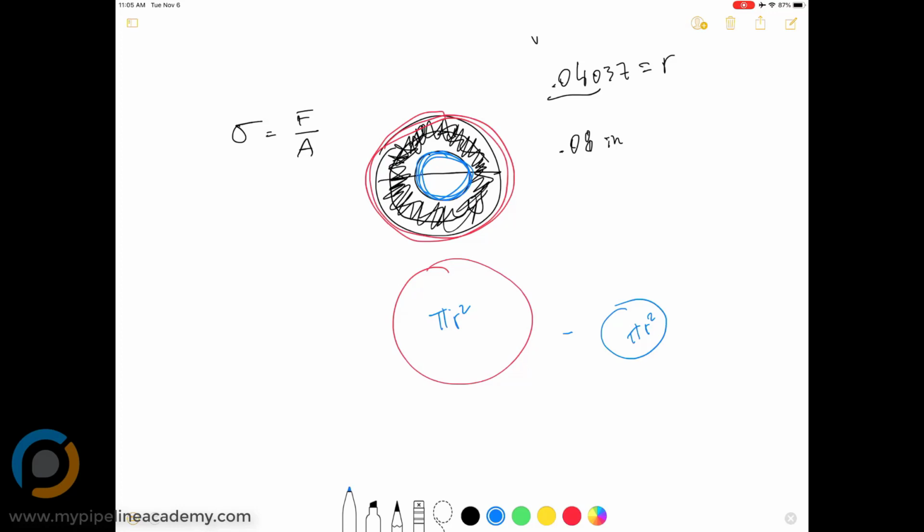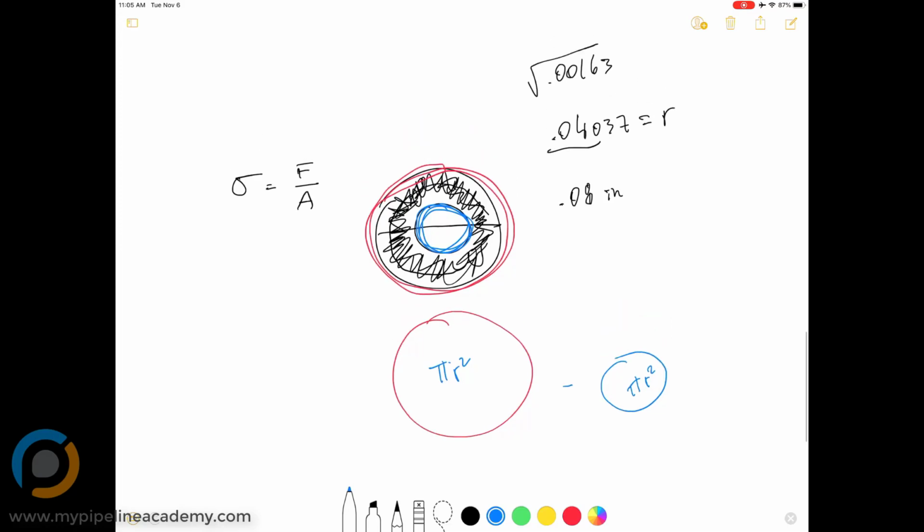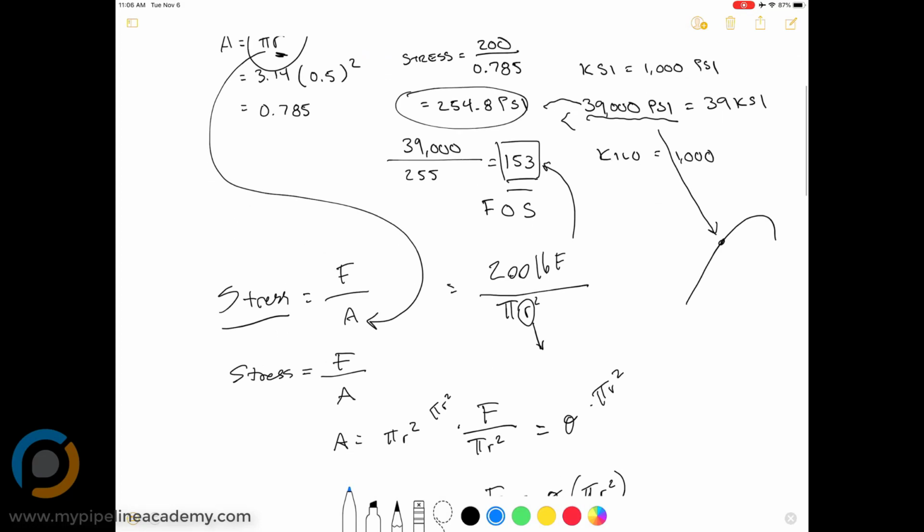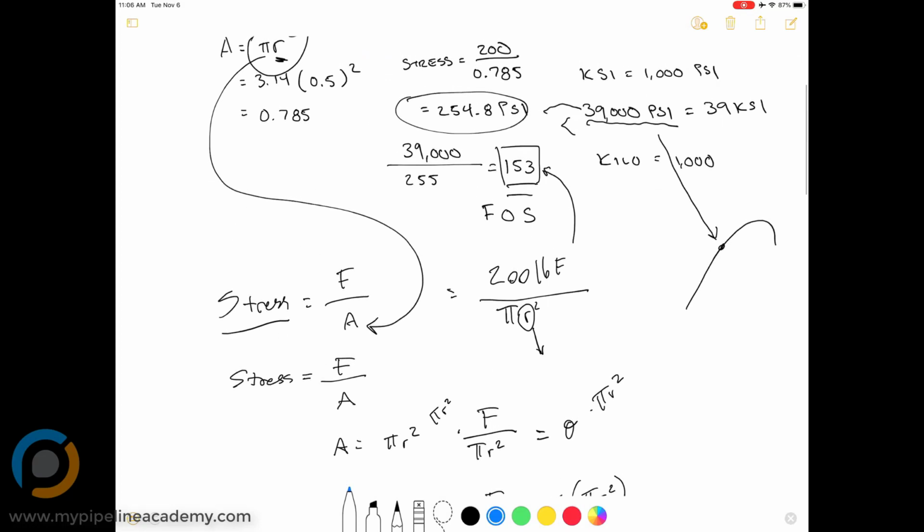Yeah. Wouldn't a website like McMaster already tell us the information such as the stress yield point? They'll tell you what the stress is, yep, the yield stress, but you need to compare that yield stress against the stress produced within your shape, right, within your rod. So you still need to calculate the stress in the rod, and to do that you need to calculate your area or know your area.